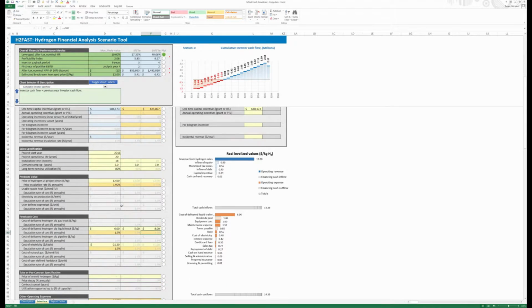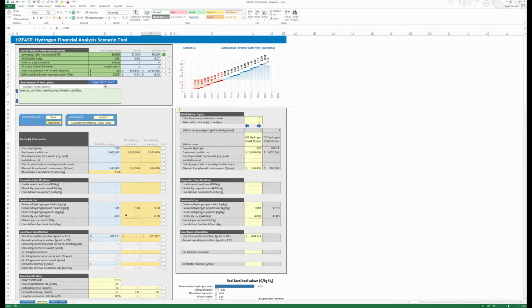Practically, you can specify as many as you want. Anything that's actually relevant to the model, it will be run. So once you specified uncertainty parameters, you click the evaluate uncertainty parameter. It does 1,000 runs by default. I've done that just in the interest of time.